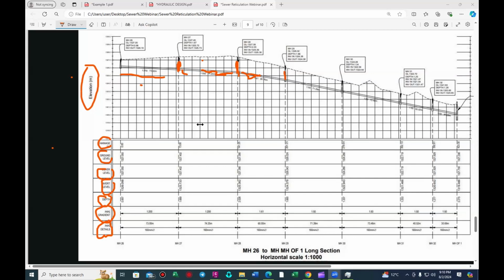Okay. Then are you the one that determines the path of the SWA line, or the surveyor? What are the considerations before positioning? I'm the designer, remember. I'm the one that actually determines the path of the SWA line based on my surface analysis. This is where design comes from. The surveyor does nothing here. You are the engineer, the one that determines the path of your design line, right? So it's the engineer's job. It's part of the design. So you have to first of all do your surface analysis, see how your flow lines are going, then decide the path for that sewer.